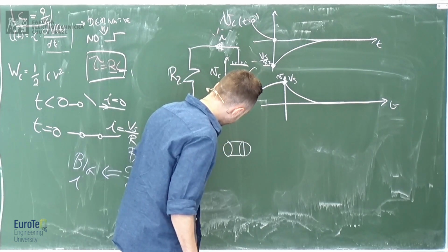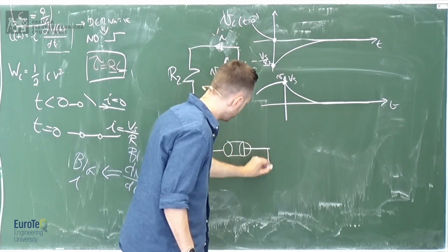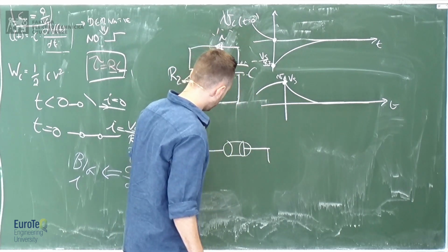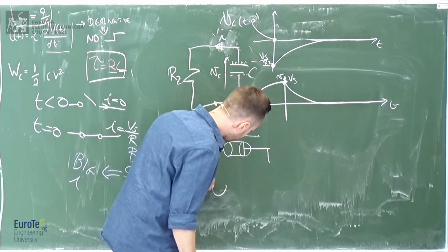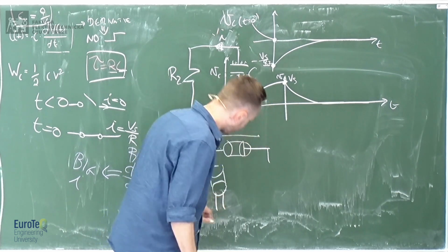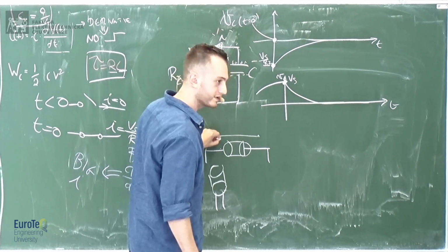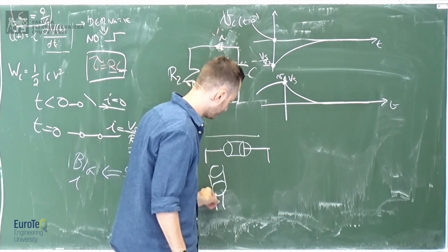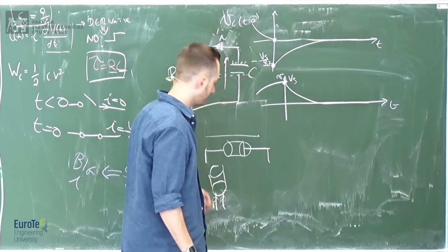You can have a capacitor that has an axial form, so it would look like that. What do you mean by axial? The leads are axial, so they go out on the axis, and then you can have a radial. I think these are the words: a radial capacitor like this, where the leads come out like that. This one has more inductance, and this one has less inductance. I understand what you meant.